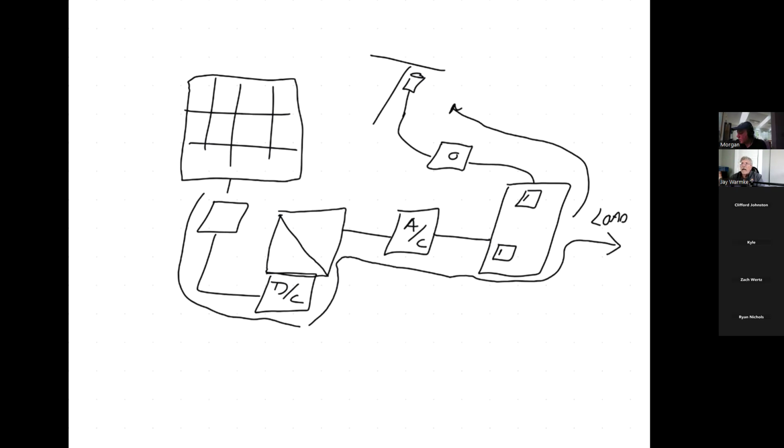5 minutes later, every single inverter that was built that's attached to the grid kicks on, and all of a sudden the demand on the grid just plummets, because now all my solar arrays are servicing my load, not the grid. So the load from the grid drops dramatically all at the same second, which causes the grid to crash again. So the grid is crashing. They're getting these cascading crashes just because they cannot predict what's happening with that, and everything's happening all at the same time with these inverters.